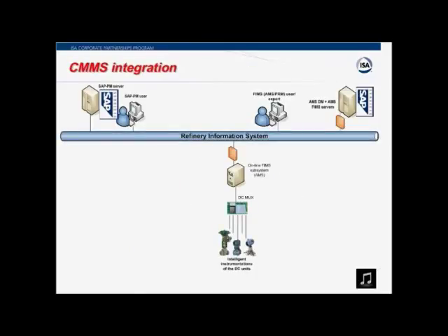But how does this system work when in use? Let me explain it with an example. Say, one of the control valves gets stuck. In this example, you can control it in the opening direction without any problem. But when it comes to closing, it is faltering. Nothing can be seen from outside until the diagnostic system detects stress in the valve. A warning is sent to the FIMS and subsystem, and so it is escalated to the level where the responsible people perform the risk-based work selection.